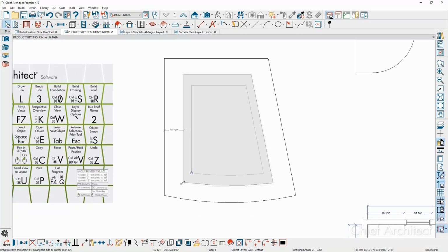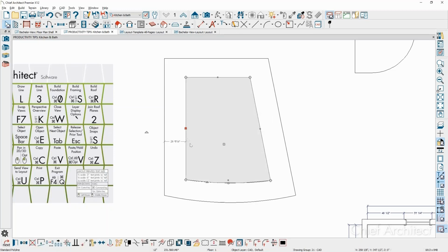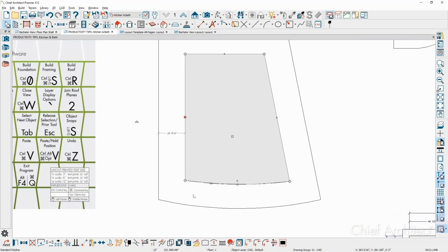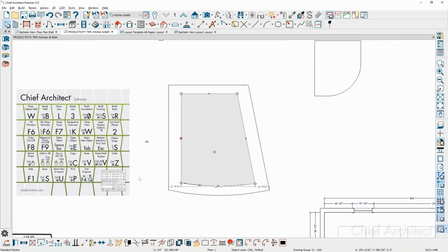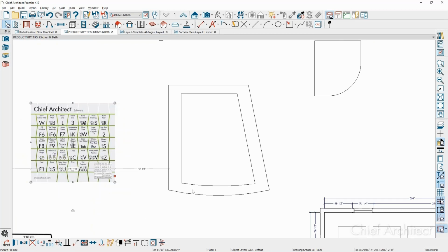And then the other tool is to hold the X down when you have that. And let's see if I press the tab key simultaneously, I might be able to actually type in an exact number, 12 inches. Nah, that doesn't work. But the X key allows you to then concentrically resize it. It works on images too. So press the X key down, it will concentrically resize.